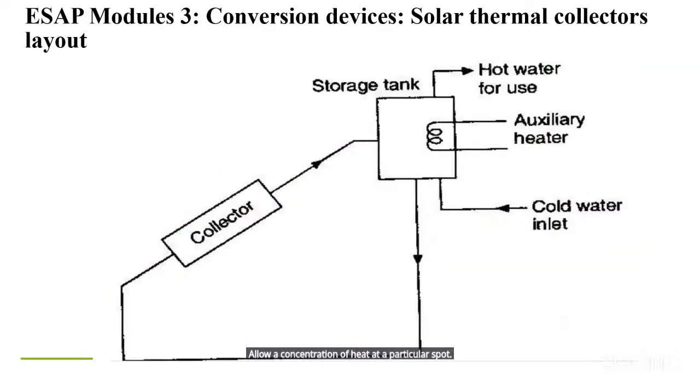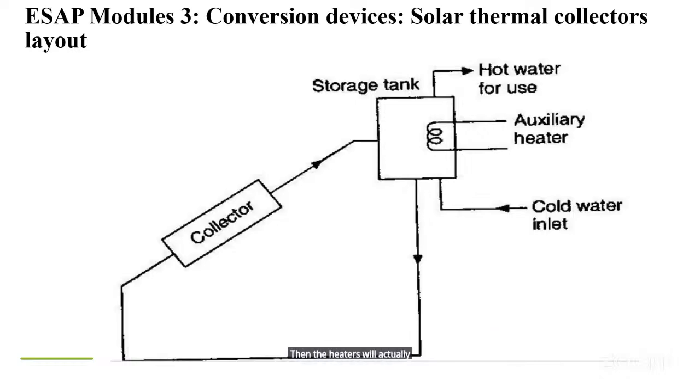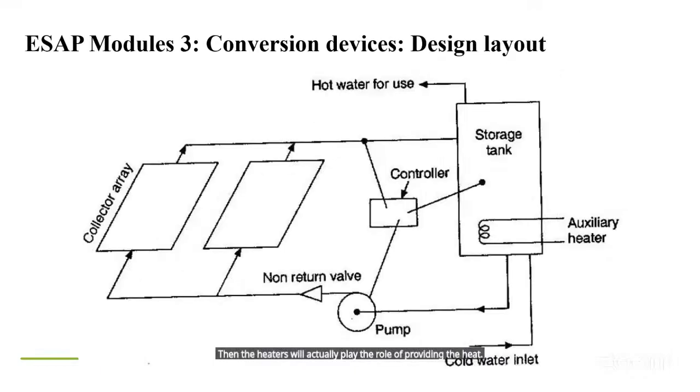So sometimes these thermal solar collectors are coupled with a number of systems. So you can have tanks, and these tanks can also be equipped with heaters. In case the collectors are not working, then the heaters will actually play the role of providing the heat for the water.